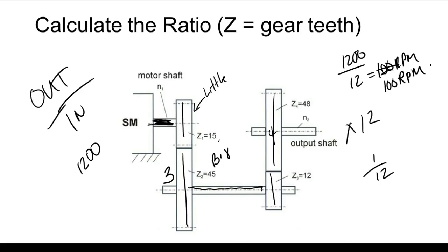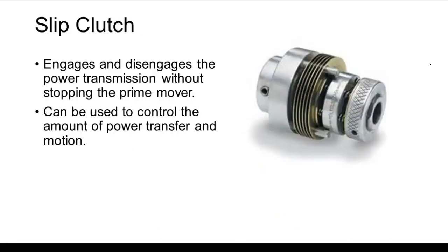Or used to, the gear shifts were controlled by vacuum. So it had a vacuum coming into your automatic transmission, and depending on how much vacuum your engine was pulling would depend on when the shifting occurred. Now your shift is done by electronics, trying to maintain the best gas mileage, torque, gas mileage ratio.